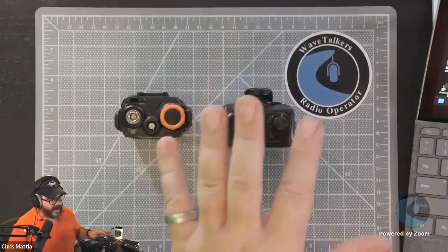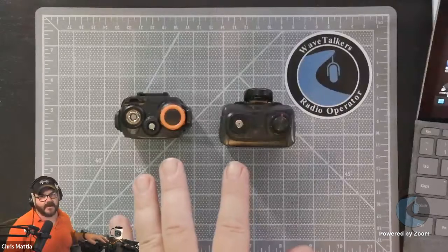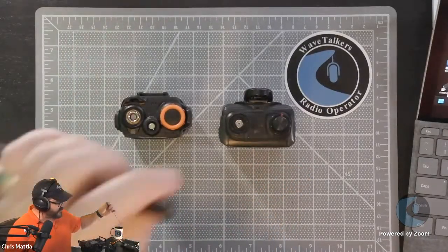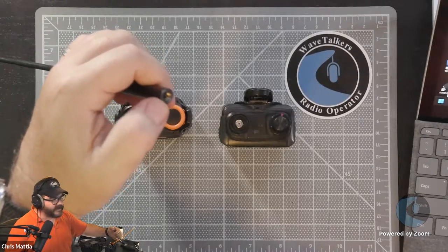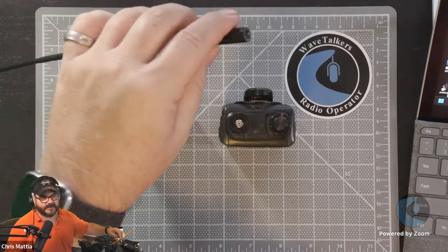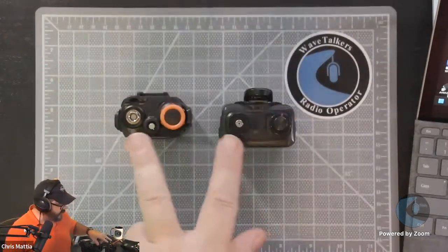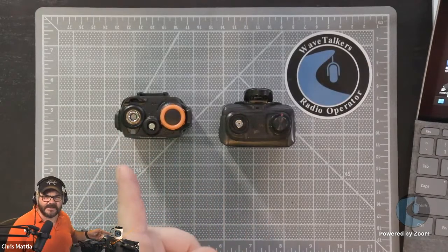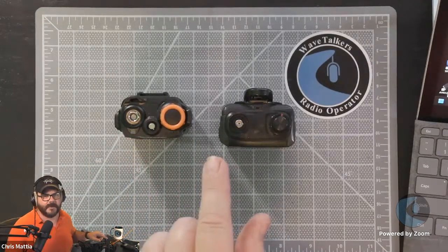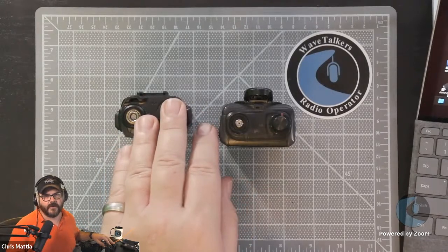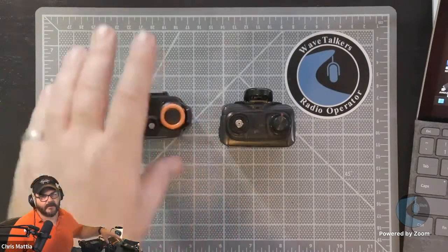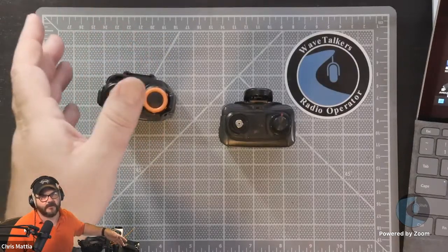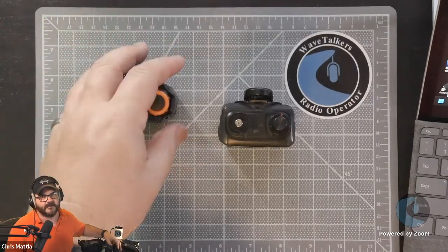One of the drawbacks to having the SMA connector is that the antenna ports are really tiny. The threads are really small, so it's very easy to cross thread these. The pins are much smaller, so it's pretty easy to bend and damage them. If you're talking about one of the low-cost radios, it's not worth worrying about, because they're usually about $20 or $30. They're pretty easy to replace.